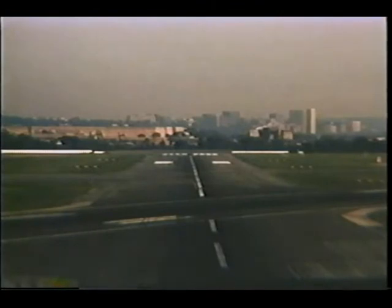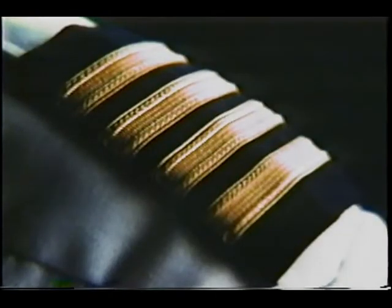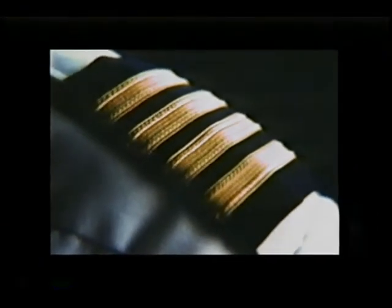Or he may ask you to deliberately land long, maybe because he wants to keep the parallel taxiway clear or to minimize your time on the runway. In any event, always be prepared to compensate your approach techniques to help maintain the flow. But never forget that you are the pilot in command. Don't be intimidated. If you feel uncomfortable about doing something or can't comply, say so. Express your pilot prerogatives.